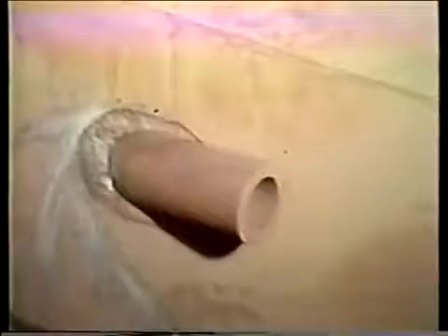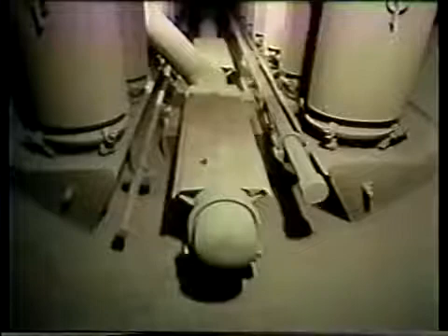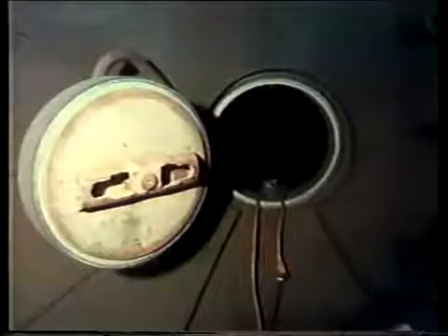Now, some specific things to check during a waterside inspection are the overall condition of the drum or moisture separator and some of their internal features. Those include the steam separators, nozzle openings, tube and downcomer openings, distributors, and manways.